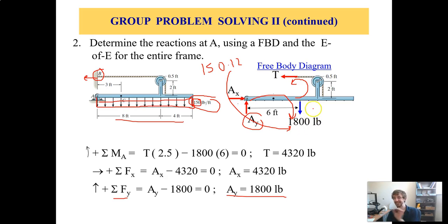As a note, just completely forget signs for the forces. Like the forces, distances, don't worry about any of the signs for that. Only look at, is it counterclockwise, is it clockwise, when it comes to your moments. That's the important detail. That's what you care about. That's where this sign comes from. It's because it has a clockwise moment, not because the force is going down. There are times where the sign can work, but it gets really wonky really fast if you start focusing on that. So don't.